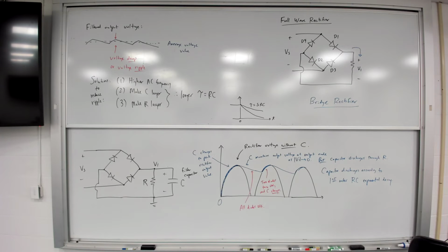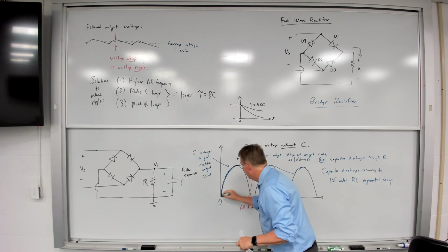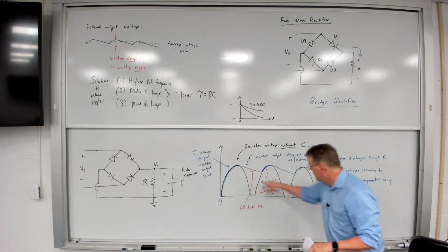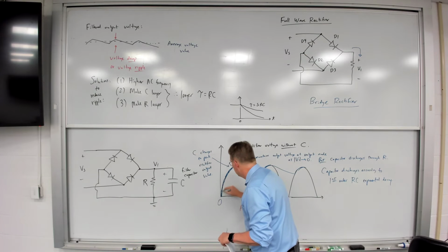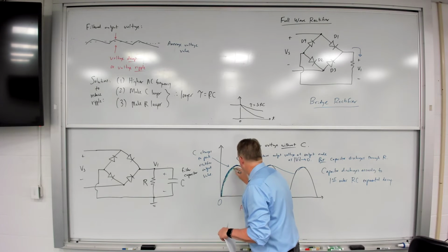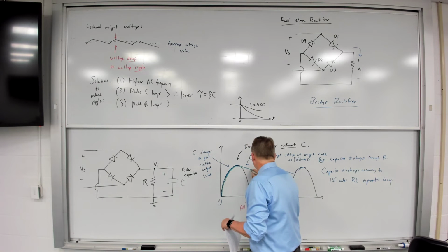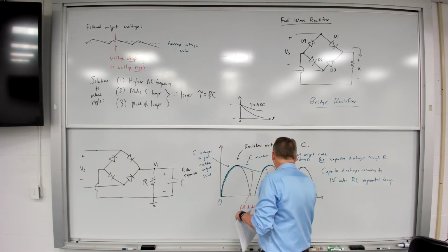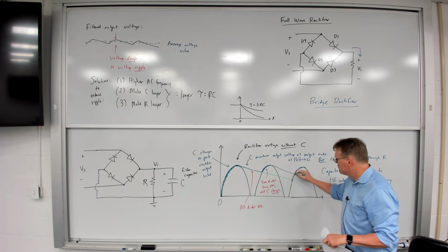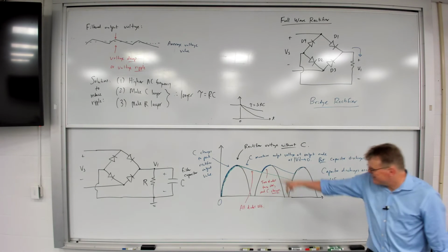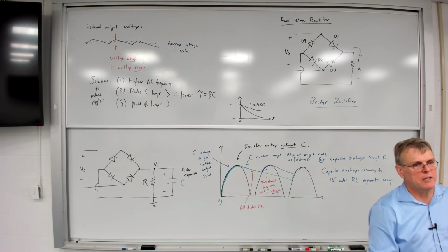Here we go. The half-wave rectifier is only going to charge up every other waveform. So if I had a half-wave rectifier, it would do this. It would decay much, much longer before it hit its recharge cycle because it doesn't have that negative-going waveform in order to recharge the capacitor.